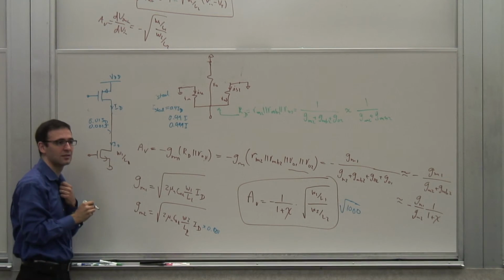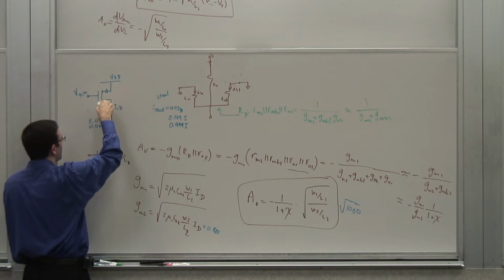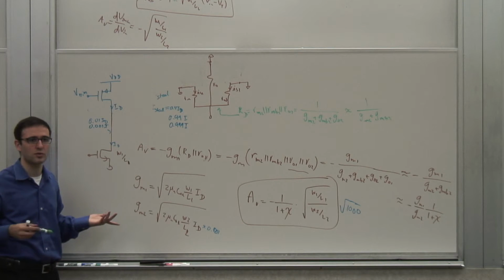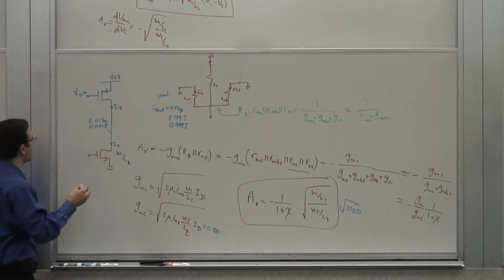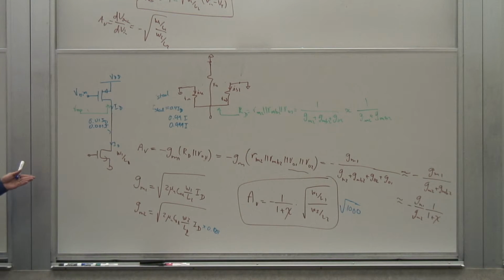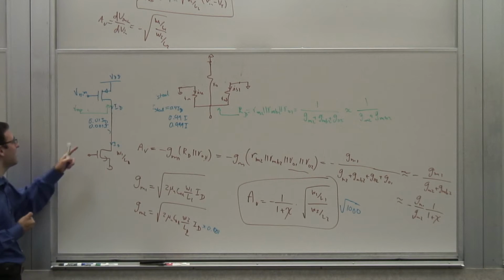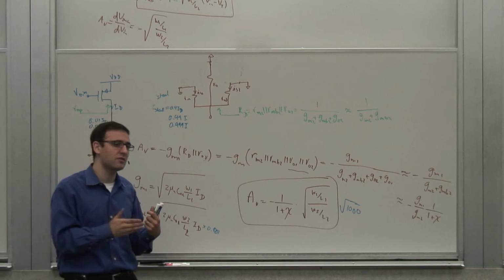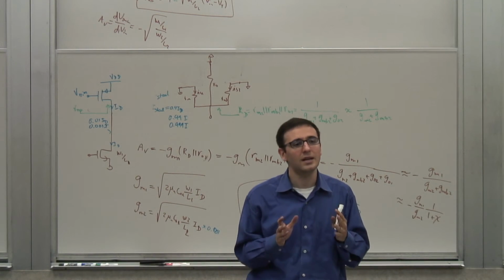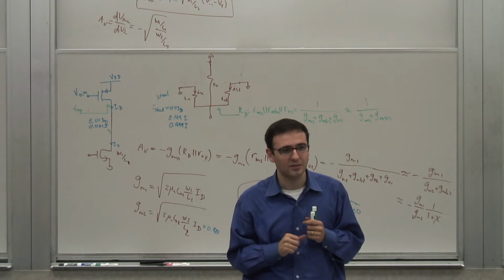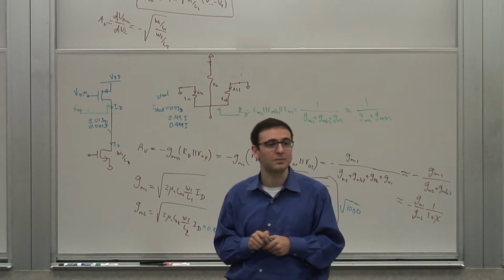like that, and let's say I keep it at some constant bias that gives me the desired current, this is the most basic, the simplest current source I can make. Because looking into here, I see ROP, the RO of the PFET. And this is similar to what we did with the bipolars. So you can see that this stage can evolve into this. Of course, it's not going to be linear anymore, as we pointed out, but it gives me more gain. It depends on what I'm trying to achieve, because there are other ways of achieving linearity. For instance, you can start off with a very nonlinear amplifier and apply feedback, and by doing that, you can make it more linear. We will see that later on when we talk about feedback.